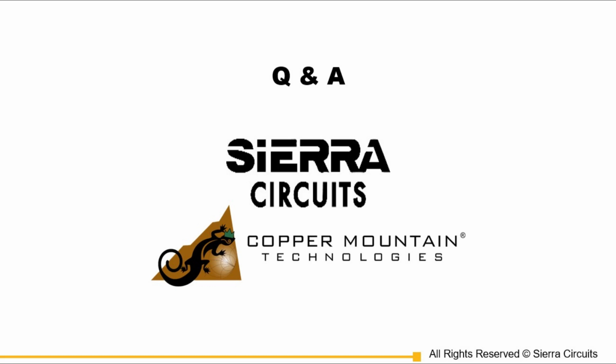Exactly right. If you do have a big ground area, you can't just leave it like that. If you have two grounds, one top, one bottom, and they're just sitting there, they're looking for trouble. They're going to talk to each other. You're going to get waveguide modes between them, maybe, or you're going to get a resonance on the top from edge to edge. They can act like antennas also. Yeah, exactly. So if you do have ground planes top and bottom, you're pretty much going to have to stitch them together everywhere, to some extent.